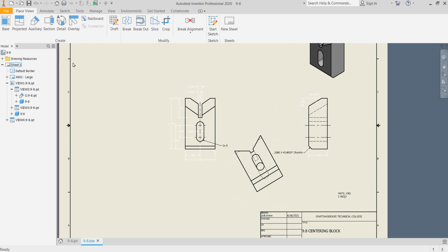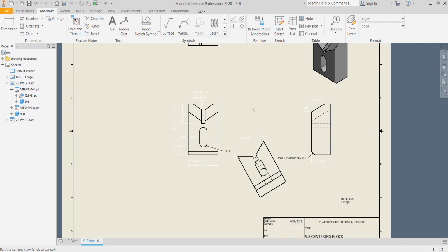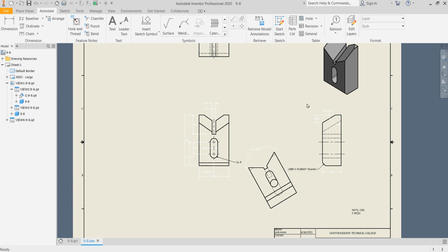So there's a true view representation of that angle. And you can go ahead and dimension that. I've got it in white, but it's 120 degrees. And you notice I pulled off of that line and pulled down, so it's working off of that line.